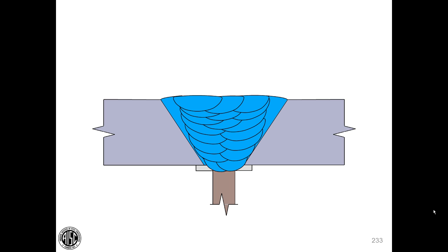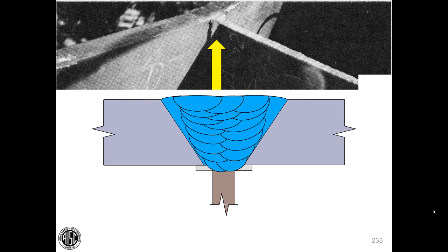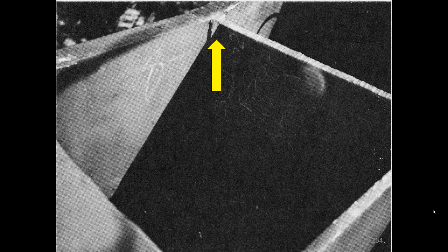Here we see a photograph of the repaired area, and you can see that the end of the weld has probably been ground or cut off here, but that's where the repair has been made, and now the thick is directly welded to the thick without having the 1 inch member intersecting through the joint. And that reminds us that we should remember or recognize material properties.